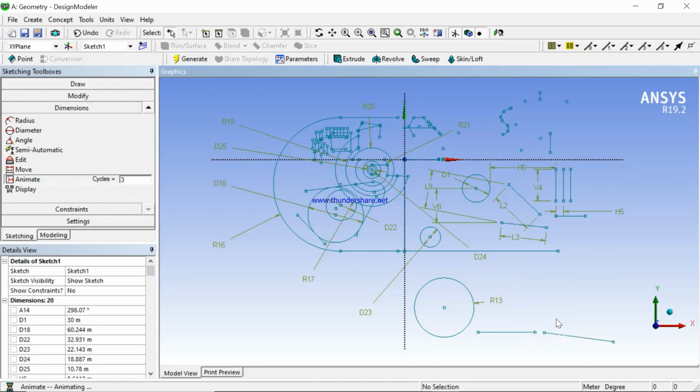Then to animate, if you want to animate a dimension, let's say this one, you can animate this dimension. You see, it is showing you that this can move because this is an angle. It can either be increased or decreased. That is what animation shows. Then we can still animate even the radius. You see, you can increase or reduce.